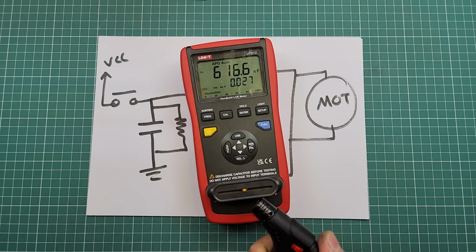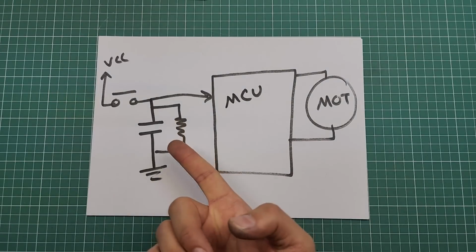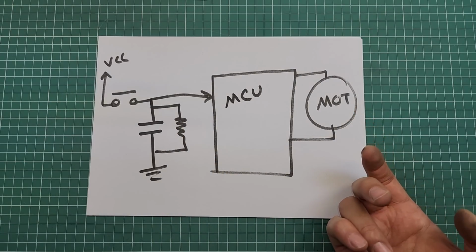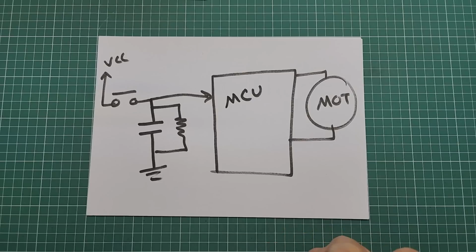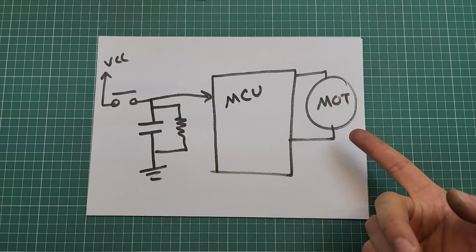Look, by heating up a ceramic capacitor, the capacitance value of the capacitor is increasing, and by cooling it down, the capacitance is decreasing. Then, if you use a ceramic capacitor here, the motor's on time will be dependent on the environment temperature, because by increasing or decreasing the temperature, the capacitance of this capacitor and consequently the on time of the motor will be affected.